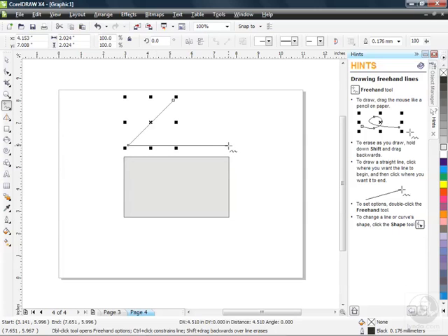That means I can actually click again to draw another line that's connected. So I'm going to move all the way over here to the right, click once, I'm over a node, click again, and come up here. And notice with Control held down, I can't actually connect it. I have to let go of the Control key to be able to go to that node because it's not a perfect angle within those 15-degree increments. So I click, and there's my triangle.